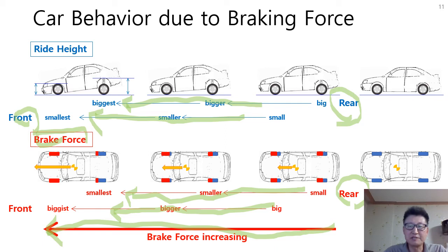The higher CG height makes both braking time and distance longer because you have to relieve the brake pressure at a relatively earlier time compared to the lower CG height. Otherwise, rear wheels lose their tire grip. Therefore, CG height should be as low as it can.